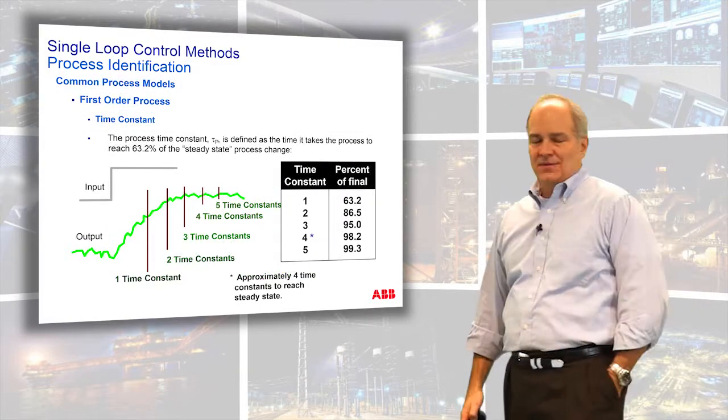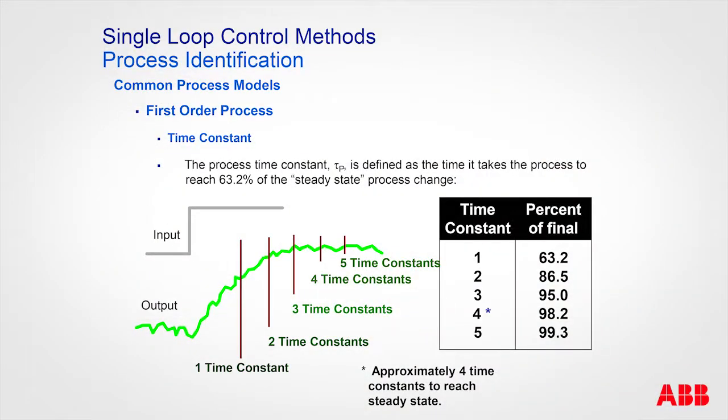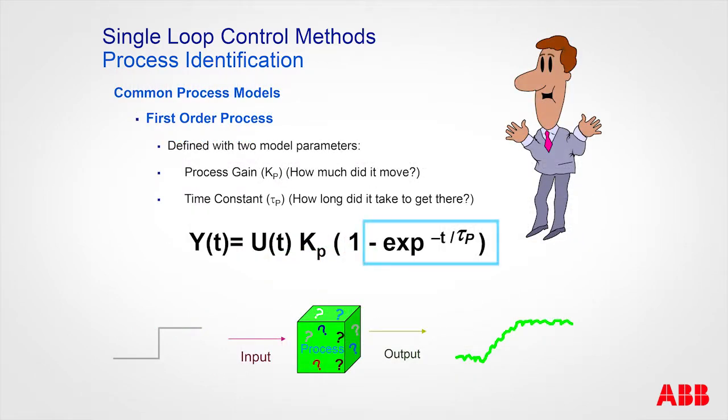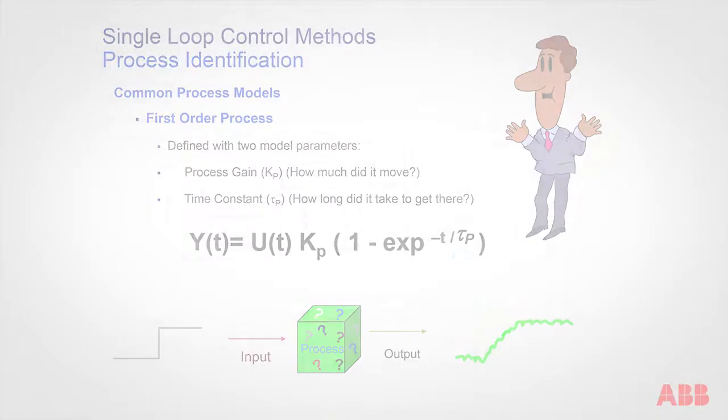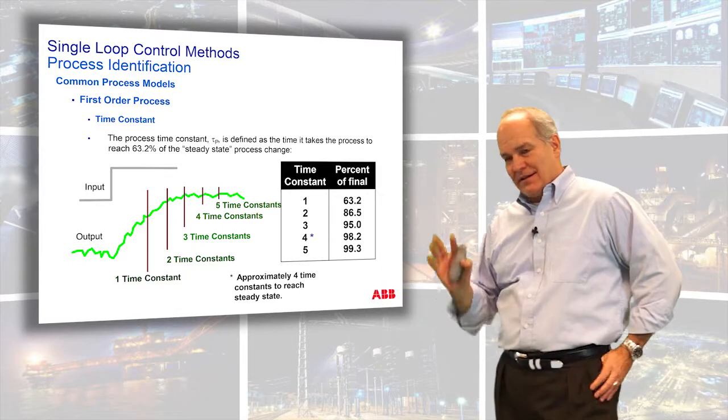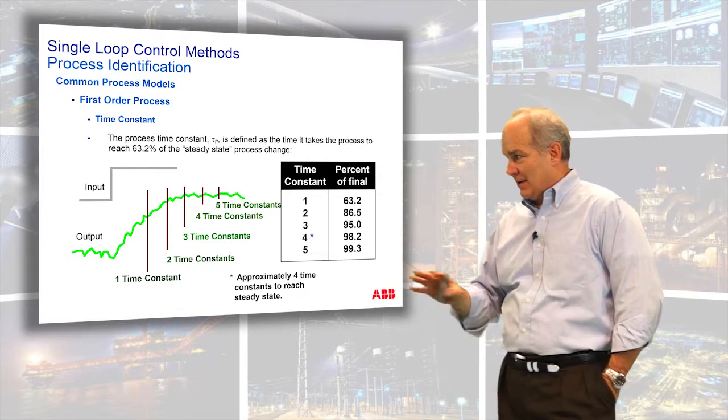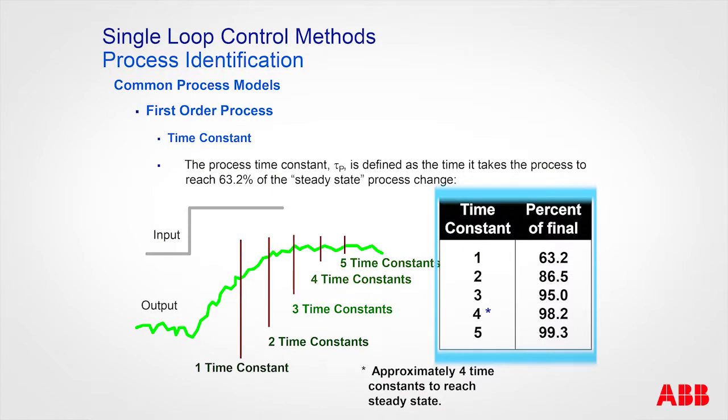There's really a couple different things. The way I like to think of time constants, because it's an exponential decay, and again, I'll just jot back here, sorry, but remember, this is an exponential decay. What you can see here is everything is related to this time constant. So everything's scaled to that. So in one time constant, where's the process going to be? Mathematically, and if you want to plug it into your calculator, go ahead, at one time constant, you are at 63.2% of where you're going. At 2 time constants, you're at 86.5, 3 95.4, 4 98.2, 5 99.3.